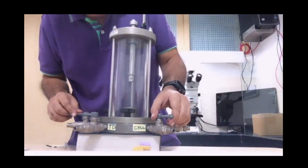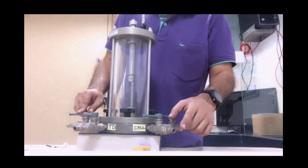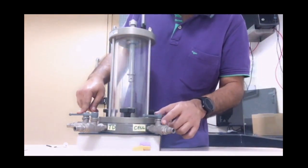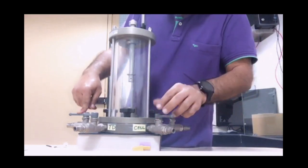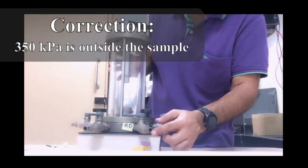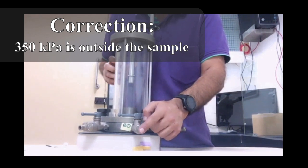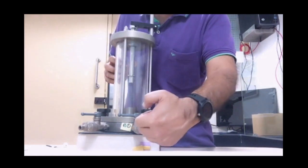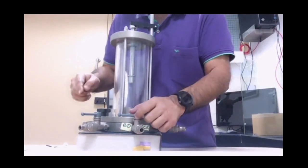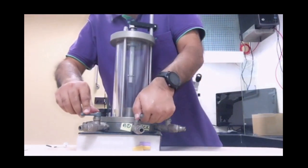Now all my valves I've got to close, so my valves are closed. My cell pressure I have increased from 250 to 350, so 350 is waiting over here. I open this out, now 350 is within the sample. That's my back pressure. For the back pressure, I had my desired value, which I have now applied, a water pressure over here of 345, which is just about 5 kPa less than over here. I open this out.